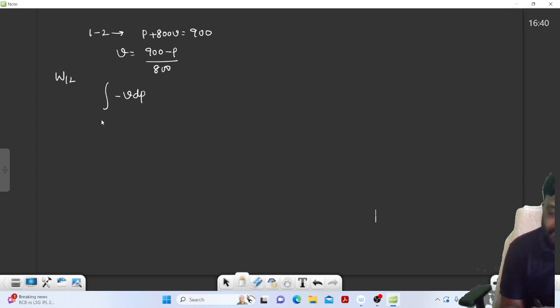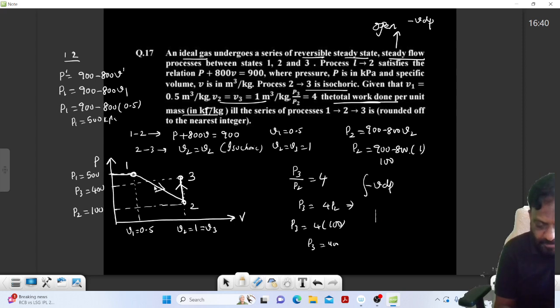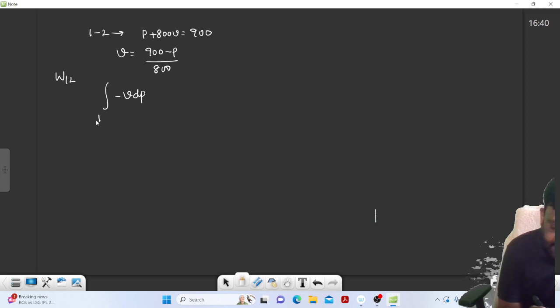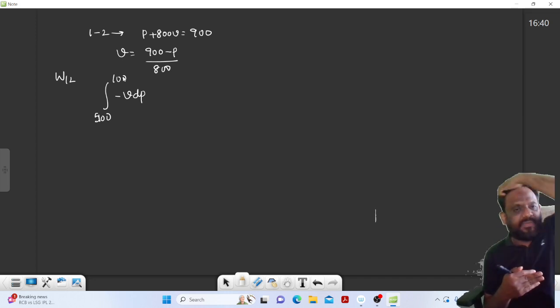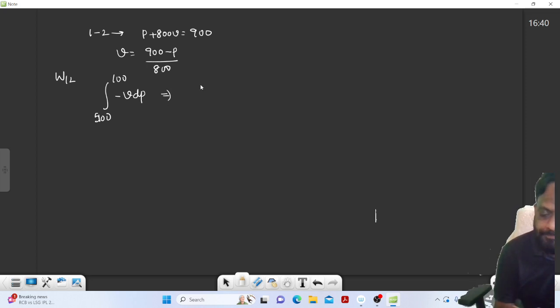Let us calculate the 1 to 2 work. Pressure is varying from P1 to P2. P1 is 500, P2 is 100. Why are you writing minus VdP? Flow work, steady flow work, is minus VdP. Now calculate. Work in 1 to 2 is equal to, listen carefully, take the minus outside. So for an open system it is minus integral of VdP from 500 to 100.